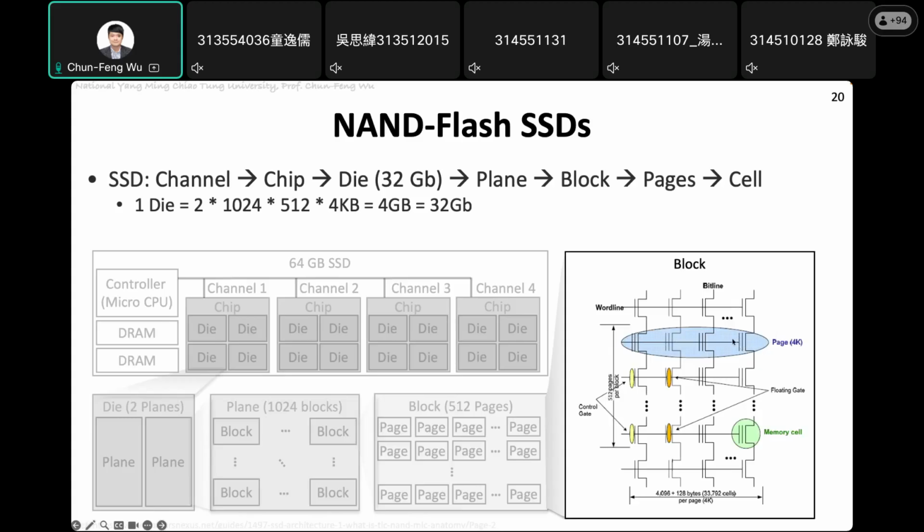Also, if you are going to program, to write data to a page, it must also align with the page level. So if you want to write something like 1111, you need to program the whole page. You need to decide to write in a 4 kilobyte area.